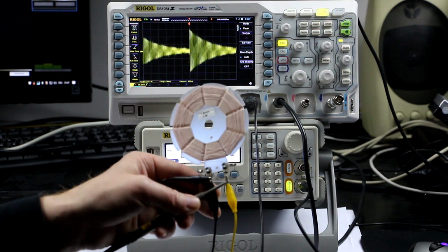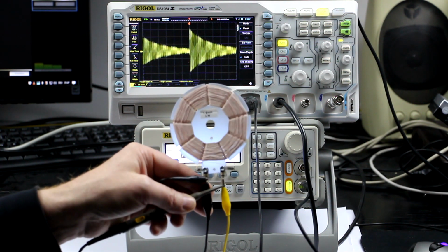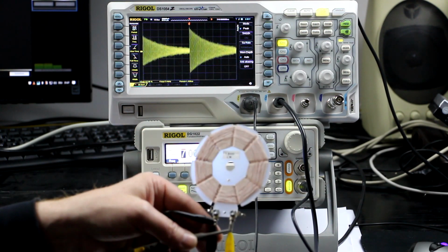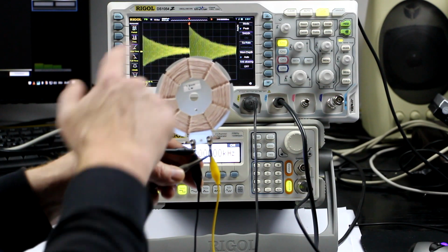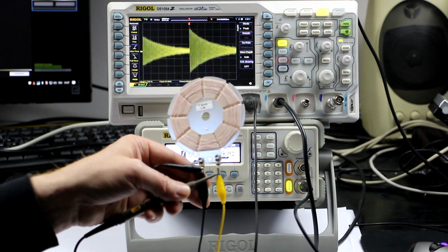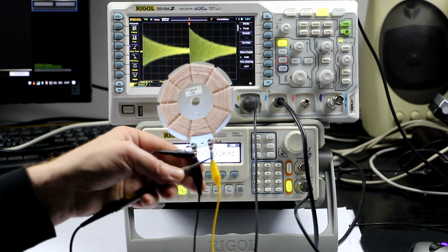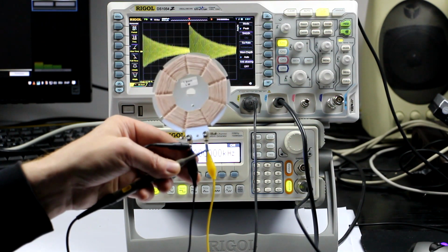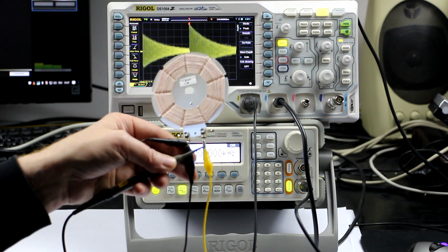As you can see here, a radio reception coil, also called a spiderweb coil, is directly connected to a square wave generator. And what do we get out of the single element inductor? Well, it behaves like a tank circuit, a parallel resonant tank circuit. And why does this strange behavior come from a single passive element in the form of an inductor? That's what we talk about today.